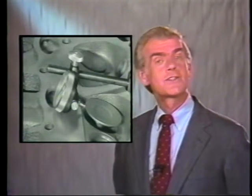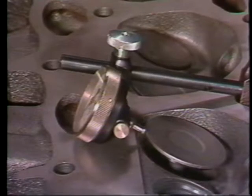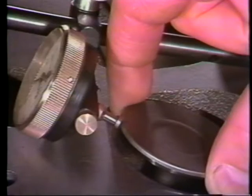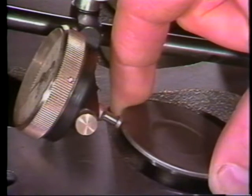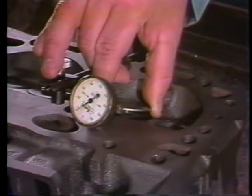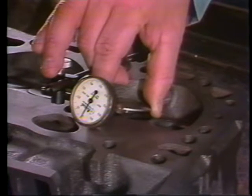For instance, the setup shown checks valve guide clearance as mentioned by response A. Valve guide clearance is the fit of the valve in its guide. This is very important for proper valve seating and oil control. With the valve held off the seat while moving the valve back and forth, the dial indicator will show valve guide wear. Play in excess of as little as 3/1000ths of an inch could mean valve or guide servicing is necessary.